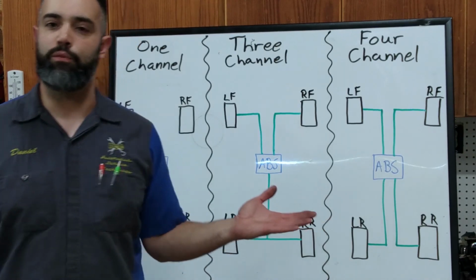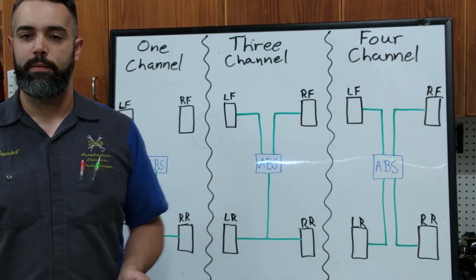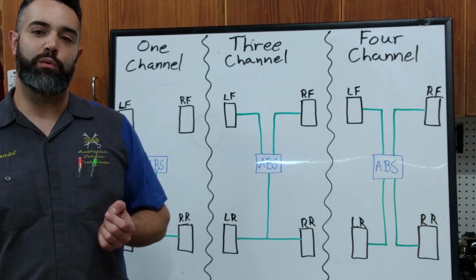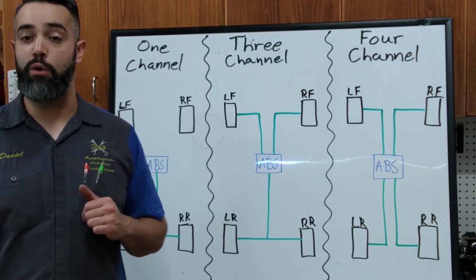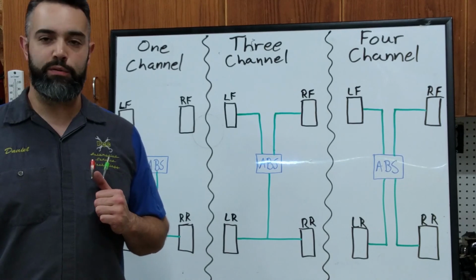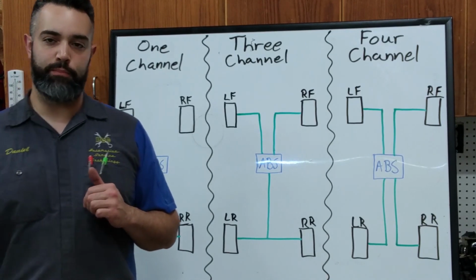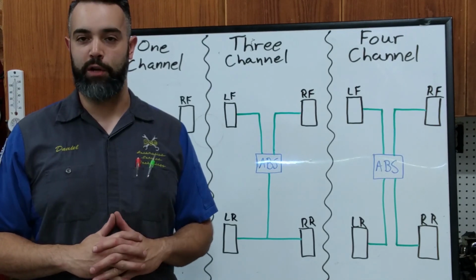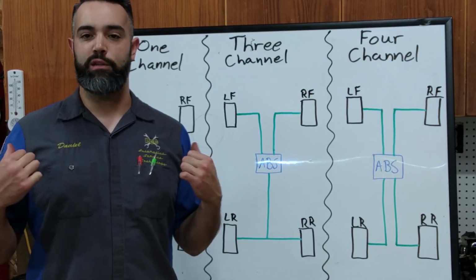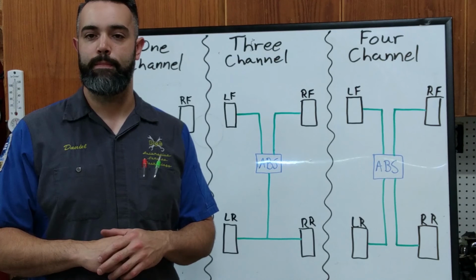Why would it be just for the rear wheels together? Let's think back to height sensing proportioning valves and what kind of vehicles those are found on. Those are on vehicles where the chassis can be loaded heavy or empty, like in a cargo van or a pickup truck, and the back end is usually pretty light when it's empty.